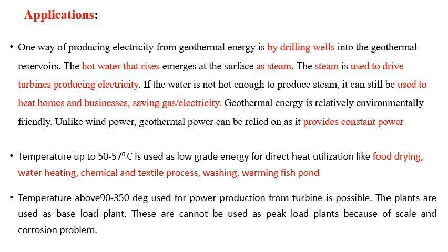Whenever we are using this, the main problem is that the water is untreated. It may have some impurities, right? And since we are not doing any treatment here, like the river water treatment in conventional boilers, it may lead to a corrosion problem. So it cannot be used for peak load plants.